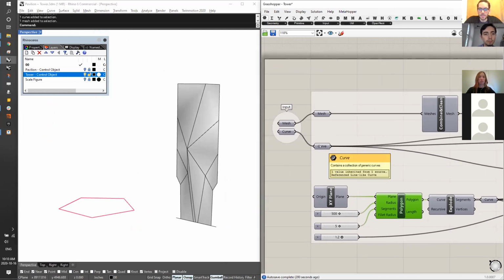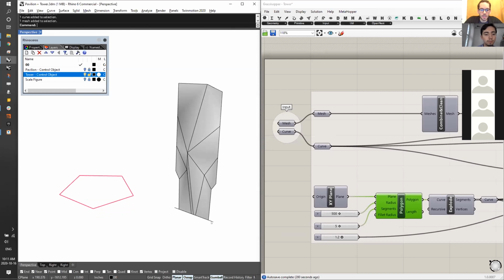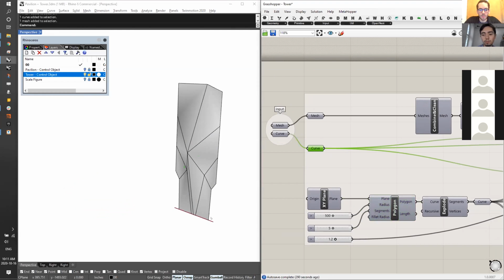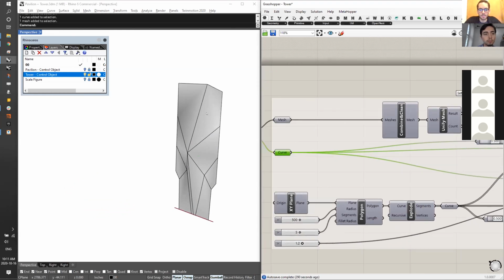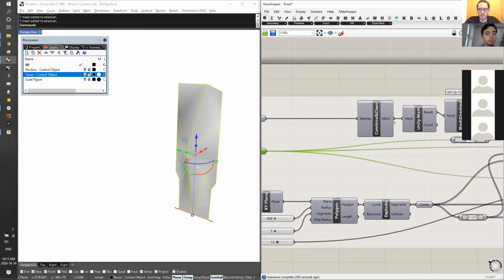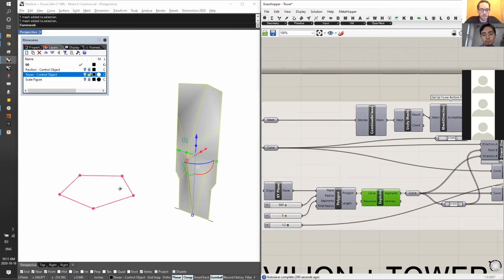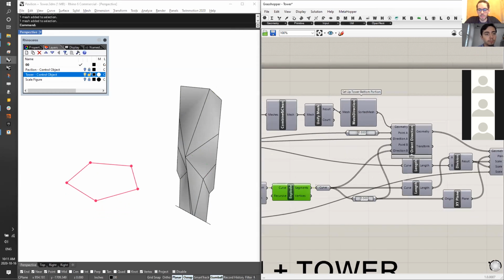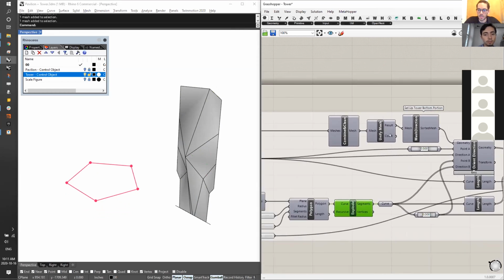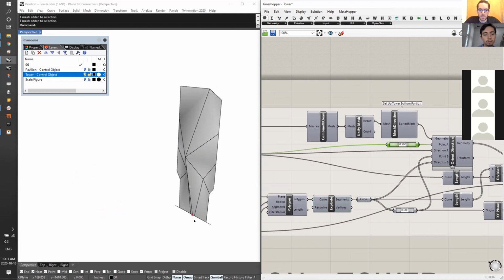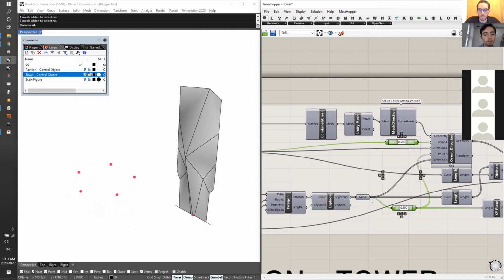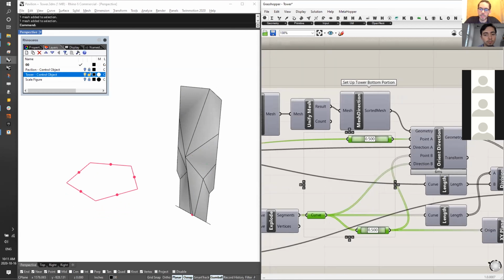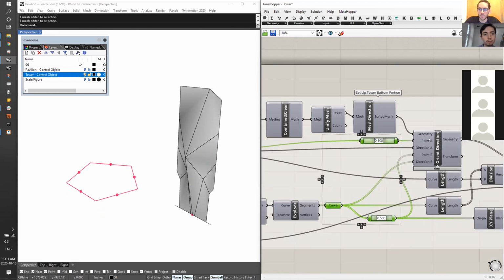But anyway, there's a polygon and there's a series of lines here. Now the line is going to inform me where this thing will sit in the polygon, and then the mesh will be oriented back onto there. So by taking a polygon and exploding it into individual segments, and then taking the mesh itself, along with the center point of the line and the center point of the polygons, we can use what's called Orient Direction. Now, Orient Direction requires point, direction, point A, point B, and so forth, and then the geometry to orient.